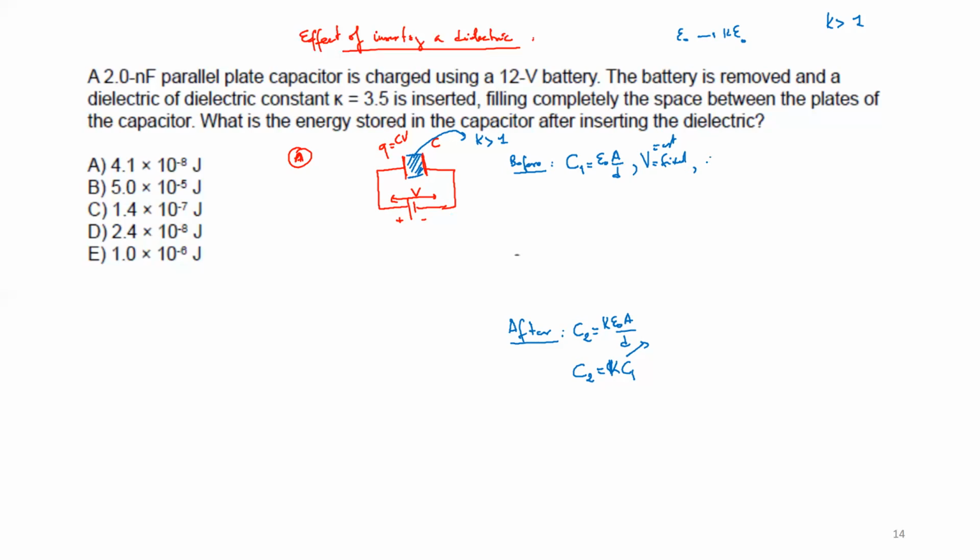So you see V1 here will be equal to V2. V2 is equal to V1 and is constant because I connect a battery to it. So the battery will keep the voltage across my capacitance constant. Now, what about Q1? Q1 before was just C1 multiplied by V.